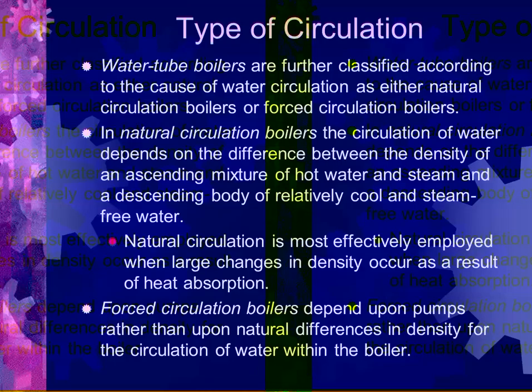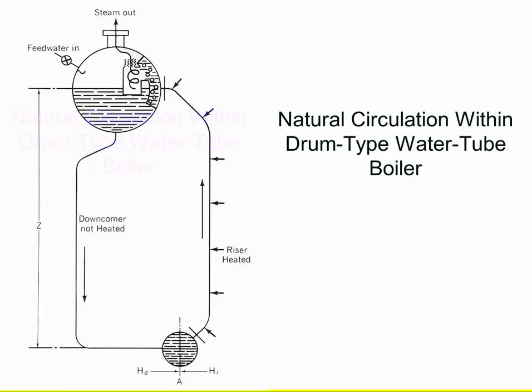So boilers are typically, another designation is natural and forced circulation. Natural circulation is the D-type boiler, where exhaust gases go, and these would all be tubes, right? As it goes through this generating bank, the forward tubes, the heat transfer would cause steam bubbles, makes the liquid lighter. So water will come down from the back tubes into the mud drum, and then that rising water comes up, and then the steam is separated in the steam drum.